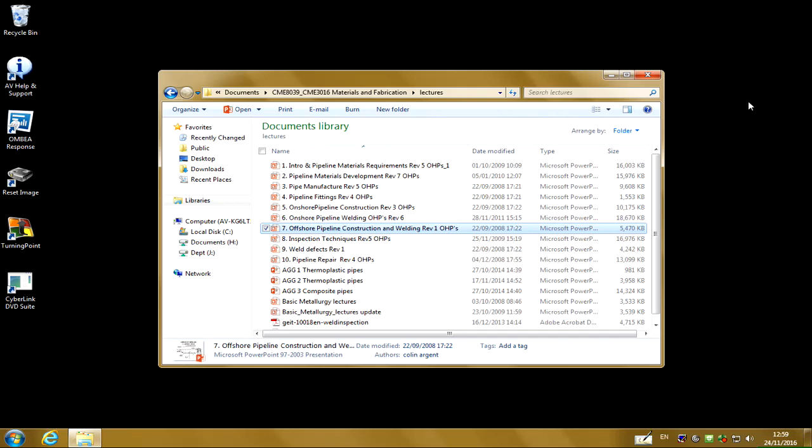The X80 consumables are not necessarily X80, they're more like X95 or something like that, or X100 even, yeah, that's right. There are different consumables for different pipes. Well, what is claimed to be an X80 consumable will overmatch X80, so it will have a higher X rating if you measure just the properties of the consumable.